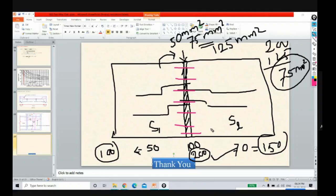And sir, one more thing about slabs. What is the significance of corners restrained or corners held down in design of slabs? Restrained and held down, both are the same. Restrained and unrestrained, these two conditions are there. Restraint means held down, providing a hold against lift of that particular corner. To restrain this particular corner, we are providing the torsion reinforcement.